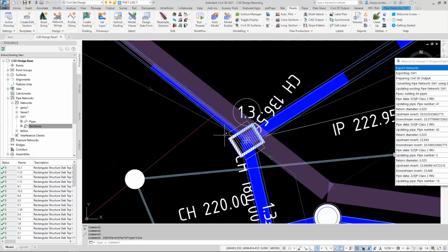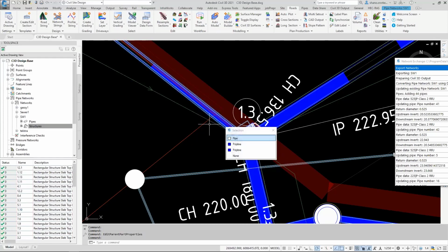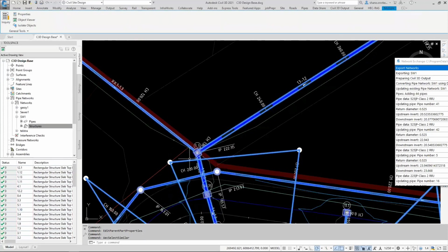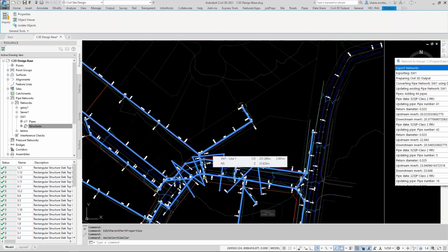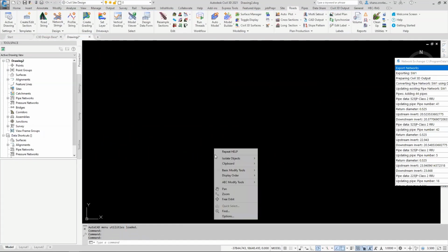In Model Viewer, there is an option to import a CAD file. So you can export those solids from the Civil 3D pipe network, put them in a separate drawing, copy and paste to original coordinates, and then in Model Viewer, you can show that CAD file. That way, if you are working with pipes and pits that are not just your primitive cubes and cylinders, you can show them.